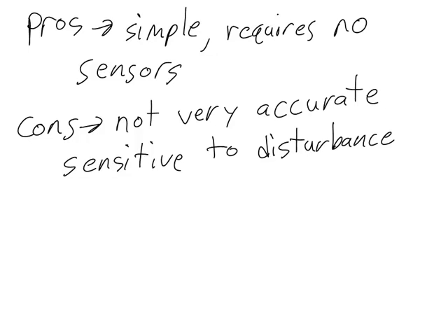When we try this in class, you will see that you are able to easily affect the positioning of the slider in your prismatic joint by simply taking your finger and bumping the slider. And when you do that, you affect the positioning, and the controller is not able, with open loop position control, to correct for the fact that your finger has come in and bumped the slider and moved it out of position.